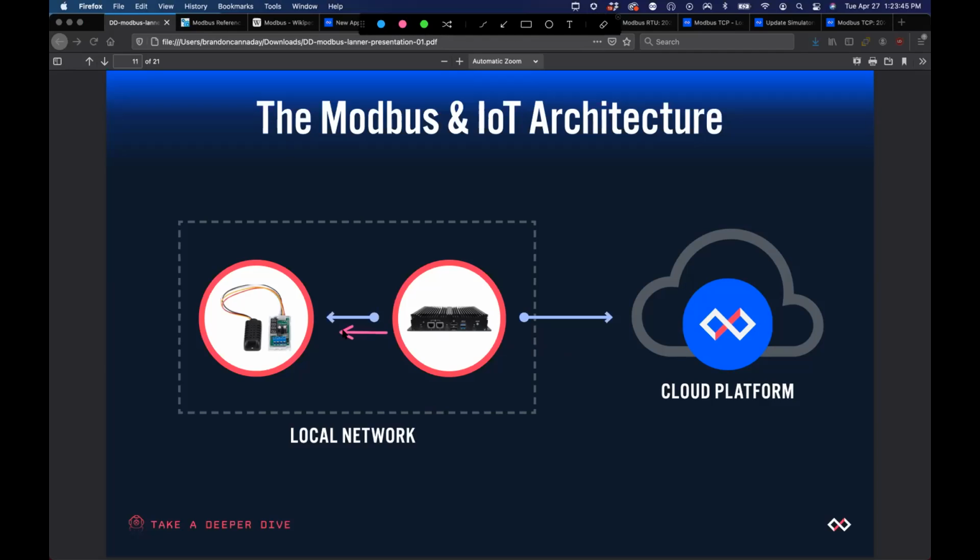The gateway initiates the connection to the server. It's the one requesting that information. Instead of an inbound connection from the cloud, the gateway makes an outbound connection to the cloud, and that's a much more secure direction. Think about sitting at your desk in your corporate office: anytime you navigate to a website, your browser makes an outbound connection to the server hosting that website, and then communication can flow back and forth. But the server hosting a website would never be able to reach into your network and make a connection to your browser. So IT departments are very happy with outbound connections like this.